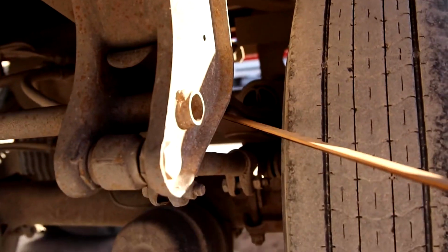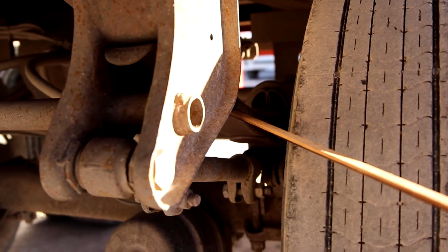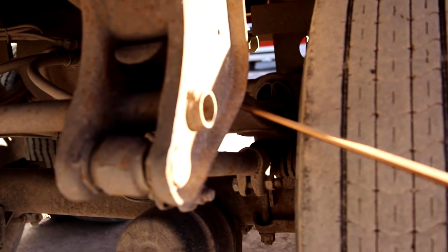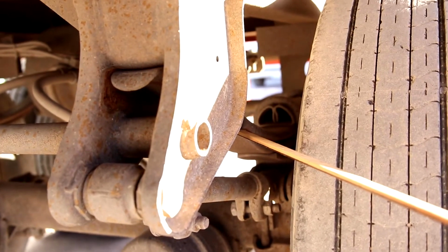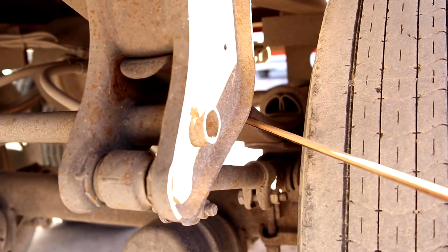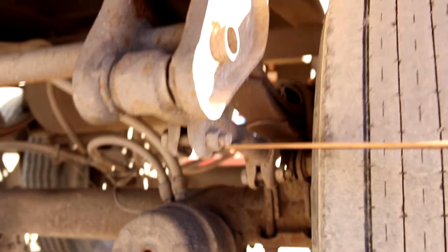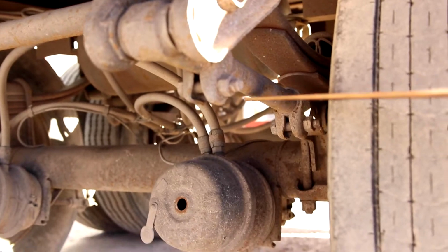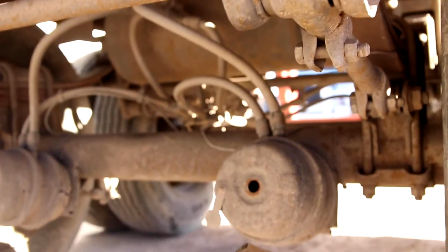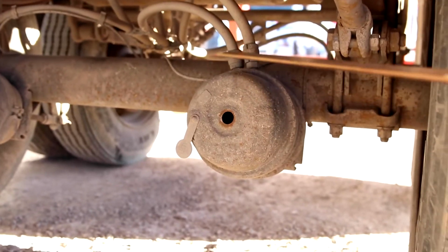The top piece here are your leaf springs, mounted securely to the vehicle. No illegal welds, not damaged or broken. No shifting, again, as they shift like a pair, from side to side, or scissoring like a pair of scissors. This is your torque arm, mounted securely to the vehicle, not missing, damaged, or broken. Now, we'll go to the braking system.